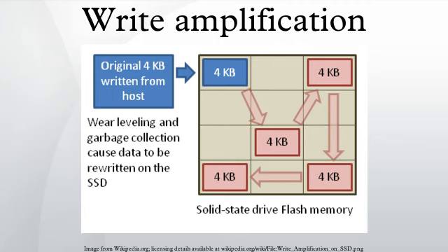Some SSD controllers implement background garbage collection, sometimes called idle garbage collection or idle time garbage collection, where the controller uses idle time to consolidate blocks of flash memory before the host needs to write new data. This enables the performance of the device to remain high. If the controller were to background garbage collect all of the spare blocks before it was absolutely necessary, new data written from the host could be written without having to move any data in advance, letting the performance operate at